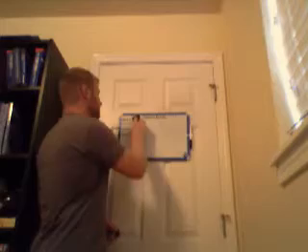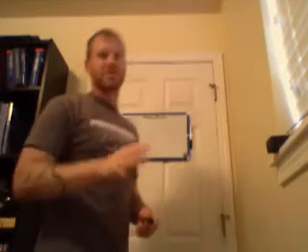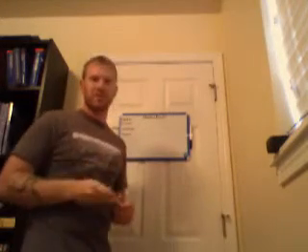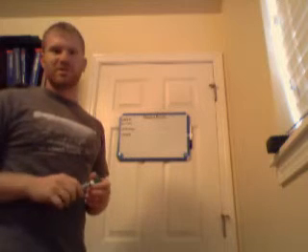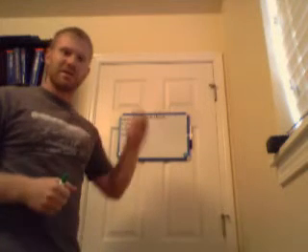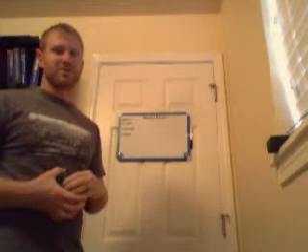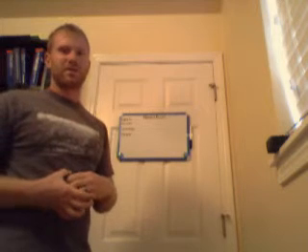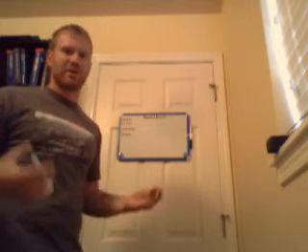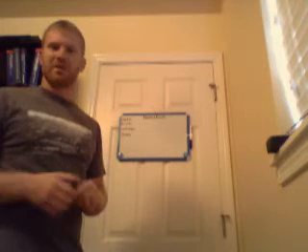So we talked about maximum gross weight. I'll just mention as well that there is a minimum gross weight for most aircraft, and that has to do with its ability to autorotate. It needs that weight to descend at an appropriate rate. And so the R-22, it's about 920 pounds, which is pretty hard to get down to with even a solo pilot and the basic empty weight of most of the R-22s around.